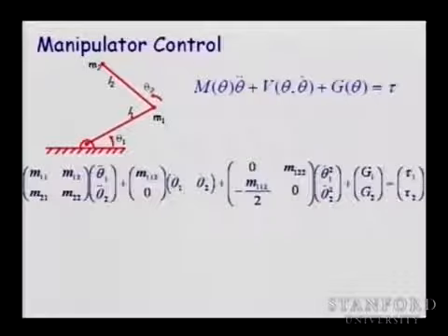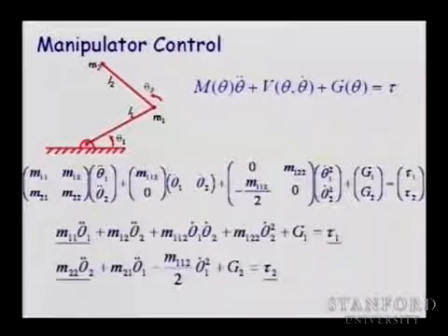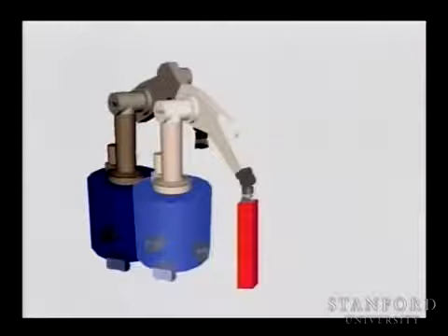And you can see that the equation of motion for 2 degrees of freedom comes to be sort of 2 equations involving not only the acceleration of the joint, but the acceleration of the second joint, the velocities, centrifugal Coriolis forces, and gravity forces. And through this, all of these will have dynamic effects and disturbances on the behavior, but we will analyze a structure that would allow us to design torque 1 and torque 2, the torques applied to the motor, to create the behavior that is going to allow us to compensate for those effects.